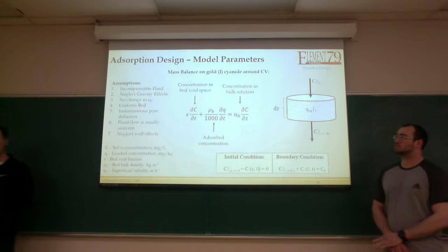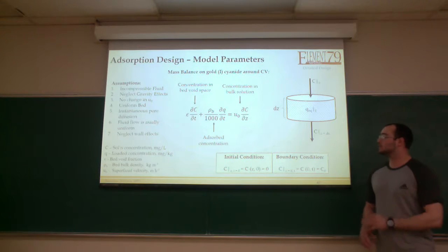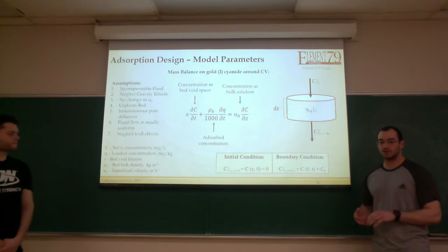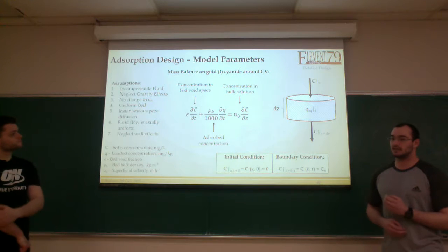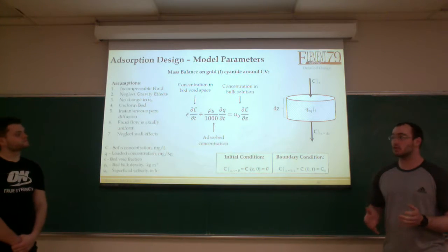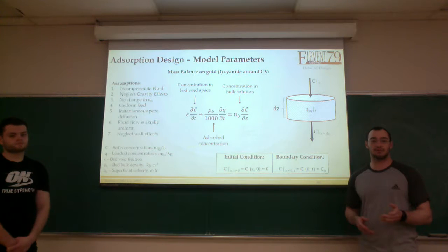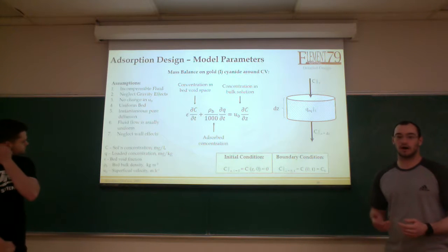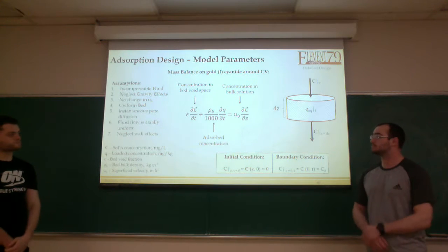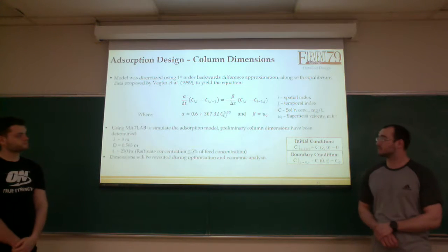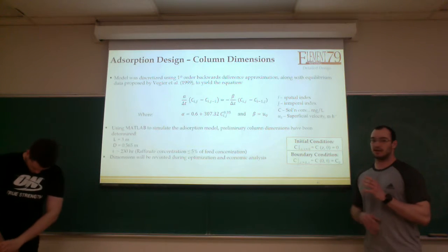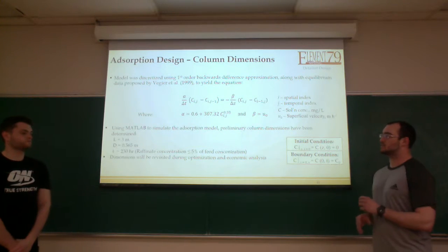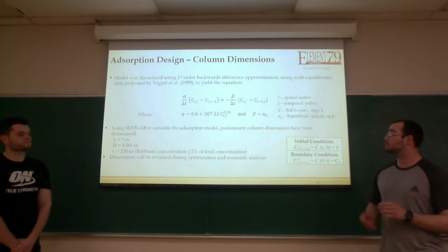So I'll go over the adsorption detailed design. Using an incremental mass balance around the fixed bed, we can determine that the concentration in the void space plus any concentration in the adsorbed part of the bed in the pores must be equal to the change in concentration throughout the bed. This gives us a model that we can use to model the process over time, because as I said earlier, it is a semi-continuous process. Next slide, please. Here we just have the model parameters discretized. We have an unsteady state equation, and we discretize that so that we can actually solve it using a code in MATLAB.